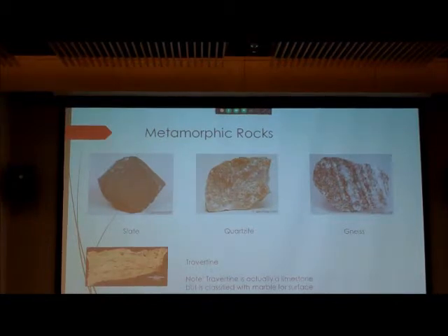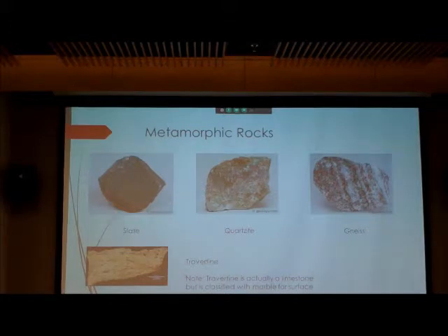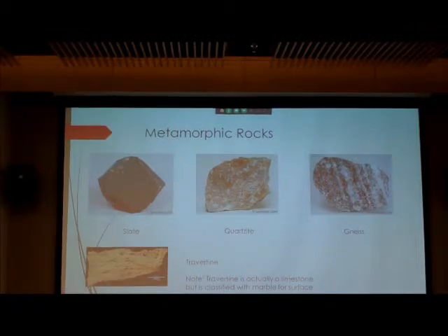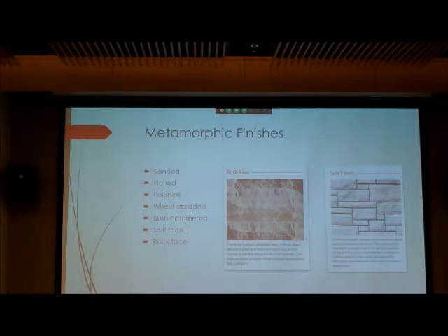And then there's travertine, which is not a metamorphic rock. It's actually a limestone, but the book classifies it with metamorphic rocks because you finish it the same way. So the finishes available for it are sanded, honed, polished, wheel abraded, bush hammered, split face, and rock face.